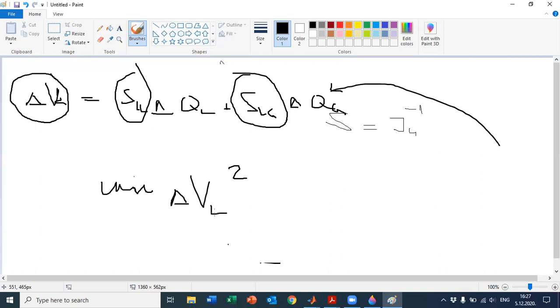So the goal is to find the vector x, which is basically the integer vector, which states the locations of the pilot nodes, which minimizes these voltage deviations. And furthermore, because we have 9 scenarios, so peak, off-peak, and middle load combined with the peak, off-peak, and middle generation from the PVs, we have to minimize the voltage deviations for every scenario.